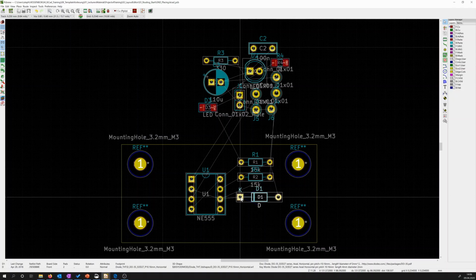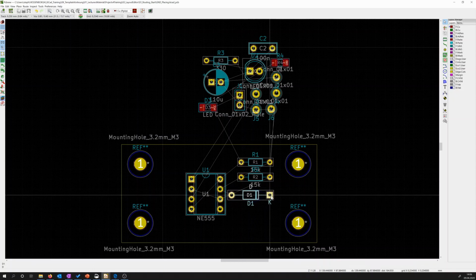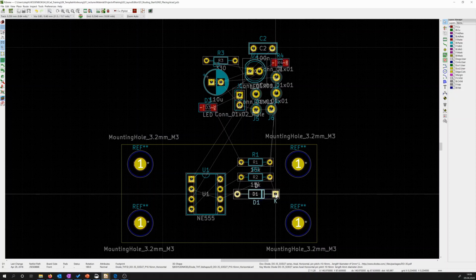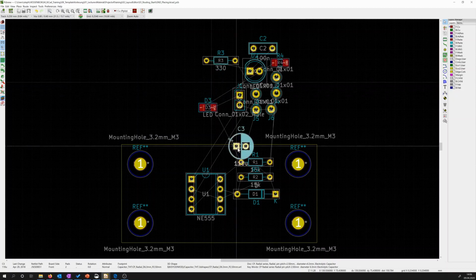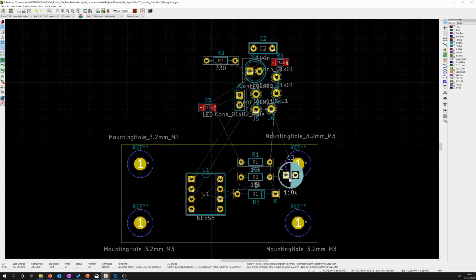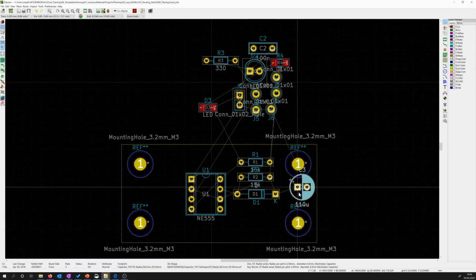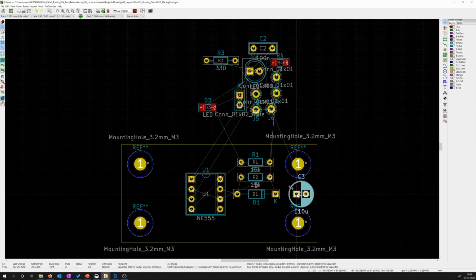So to make the connection neatly together, we turn the component so that these pins are on the same side, threshold pin THR, like this. And now we have only left our capacitor C3, threshold to ground, and we can, for example, place this component here. Well, first let's place it here and have a closer look now at our fly wires.